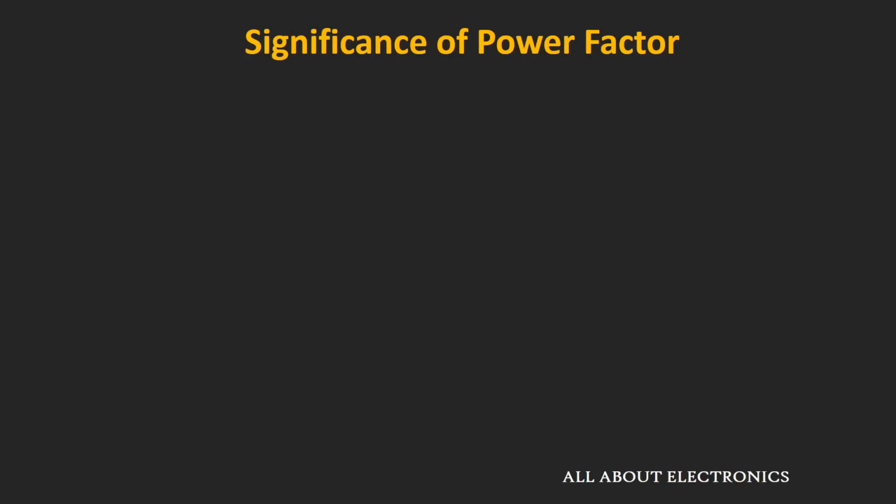When we have a poor power factor, it means we are drawing additional power for the reactive element across the load. And this additional power means we are drawing an additional amount of current. This additional current will introduce a voltage drop across the cables, which means we will receive less voltage at our homes and offices. All of this is basically an additional burden on the power supplier.